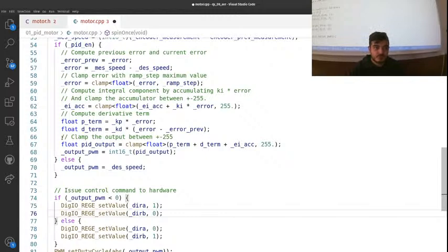It's like an ABS brake, but no. Your colleague is asking, is it like an ABS brake? No, the ABS brake doesn't work this way. The ABS brake works with encoders attached to your machine, and probably an IMU or something that estimates the current velocity of the vehicle. When are you skidding?